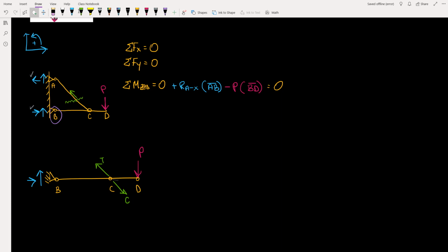So the internal force that is in the rod from A to C is going to pull up and to the left on our free body diagram below. And of course the other way to evaluate this is by looking at our sum of forces in the x direction equation for this cut diagram down below. Again, the horizontal component of this tensile force is to the left, and so it balances out our reaction at B that we already know is to the right.